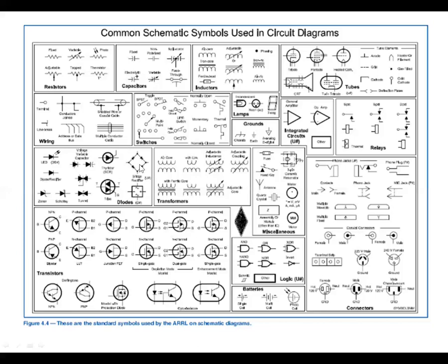You use that a lot in power supplies and motor controls, at least in industry. What you can do is take this SCR and use it in that bridge configuration rather than just a straight diode. And then by controlling that SCR, you can control the DC power coming out to control a DC motor.